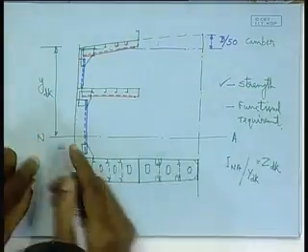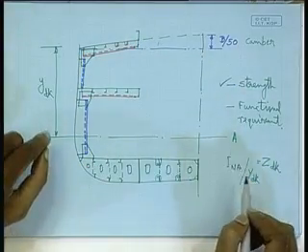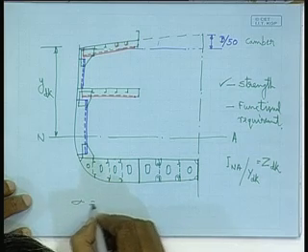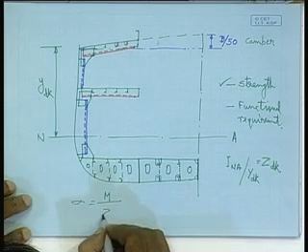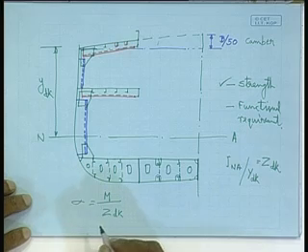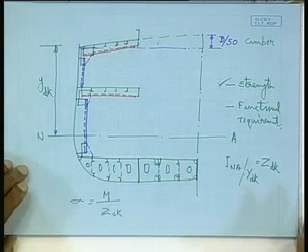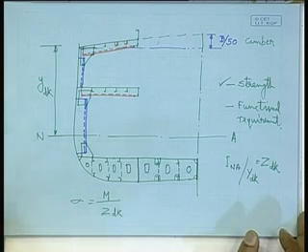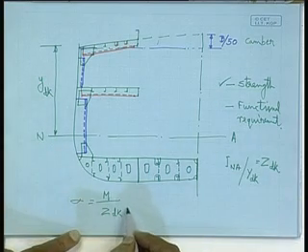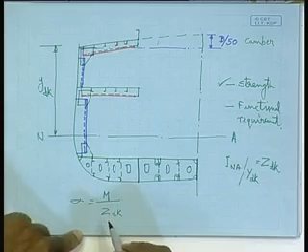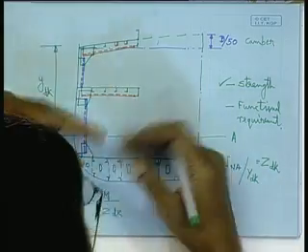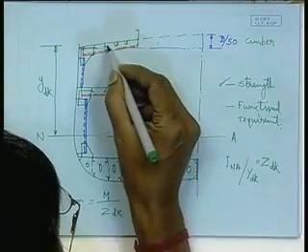But after doing that, you have done the calculation of I about the neutral axis divided by this, and you find the stress which is coming is more than the permissible stress. So, then what is to be done? That is not permitted. You will have to keep the stress below this, means you have to increase this. Z deck has to be increased, or in other words, I NA has to be increased, means you will have to take a relook at the arrangement, and you will have to see that, well, scantlings are to be increased.